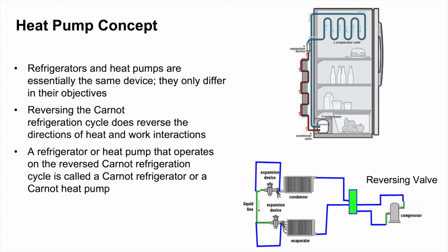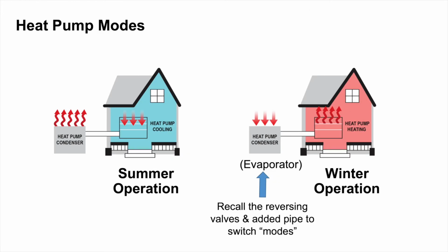So a real life application of this, let's talk about your house. Many of you may have a split unit or have seen these in more residential applications where there's a condenser that sits outside rejecting its heat with its fan. And then there's another component on the wall up high where the cool air is coming from. This is your heat pump, the two pieces with the refrigerant piping connecting between the two. And in the summertime, we like to think of air conditioning as the removal of heat from a space. The evaporator is removing the heat from the room in which you're keeping cool and rejecting that heat through the condenser, which is sitting outdoors.